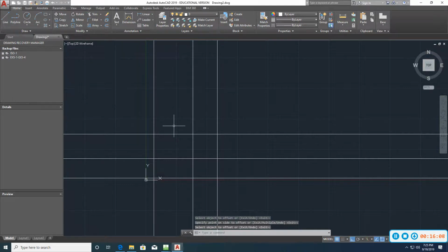Okay, looking down on this block, what is the depth of it? Can you tell what the depth is? Is that a missing dimension here? It's 40. I would take off points for that. If the way they dimension that, I would take points off of that, right? So it's 40. The depth is 40 also. So type in offset, and then type in 40.